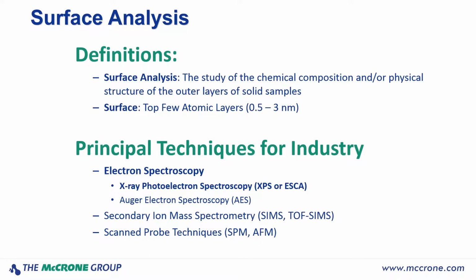Why this technique is widely used is it has some advantages over other surface-sensitive techniques. You can analyze non-conductive samples relatively easily. It uses an X-ray beam to irradiate the sample, so you don't get as much charge buildup as if you used a charged particle beam. Also, the technique provides chemical information, not just elemental or structural information, and we'll see an example of that later in the presentation. And finally, quantification is relatively straightforward with XPS using standards. So the scope of today's webinar will be XPS analysis of industrial samples.